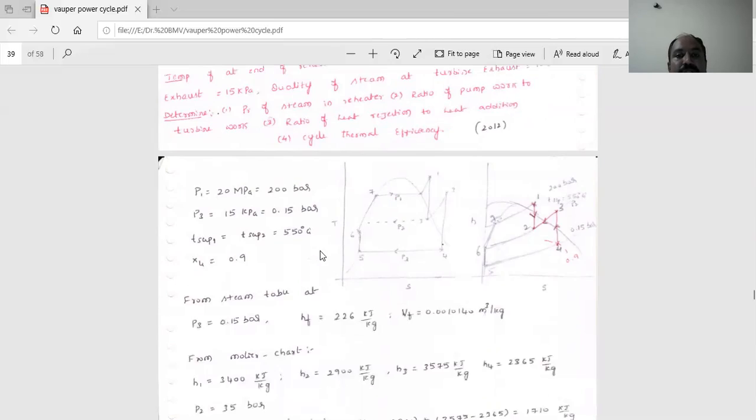We have to write down that reheat cycle. Okay, then 1 to 2, it becomes wet steam. So that's why within that curve we should write it, here also in the HS diagram at point 2 we have to write a wet steam. Okay, not dry saturated steam. Dry saturated steam at point 2 would be exactly on the curve, but it becomes wet, so point 2 is within that curve. Like that only we should write down the TS and HS diagram. That is very important in the above problem also and this problem also.